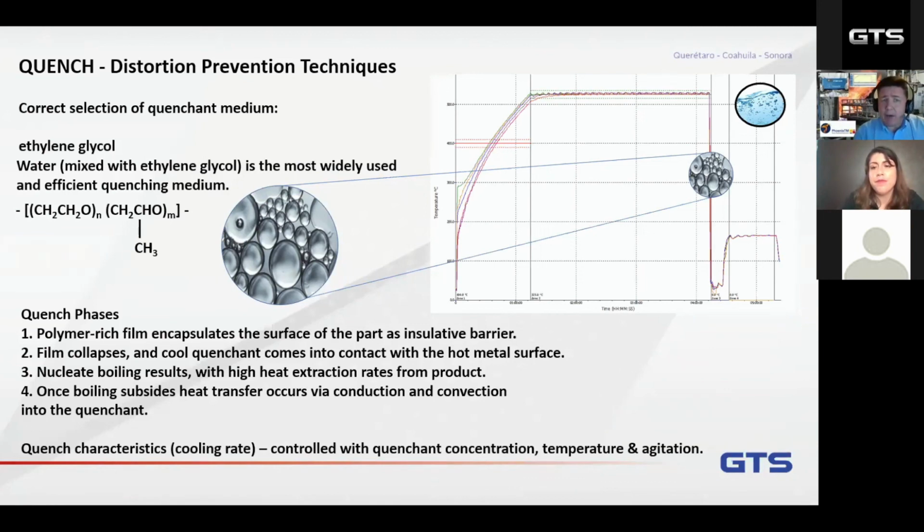Not really, as long as, obviously, there's a challenge associated with actually cleaning things down. You may need to change the insulative blanket more often, because once the glycol gets impregnated into that material, it may compromise the performance a little bit, but you may be able to wash some of that off. I don't think it's quite as bad as oil, as I'll describe later, but you have to maybe be a little bit careful.